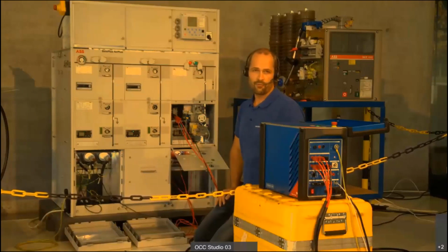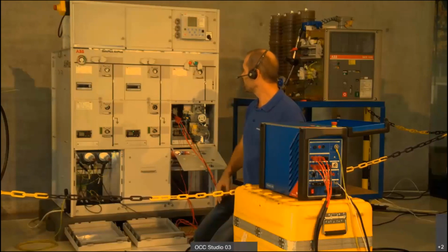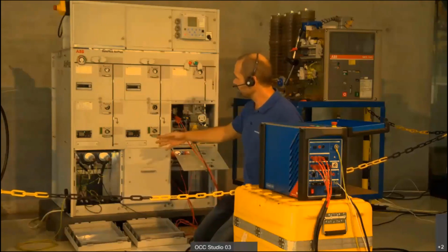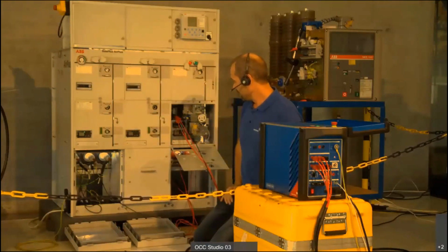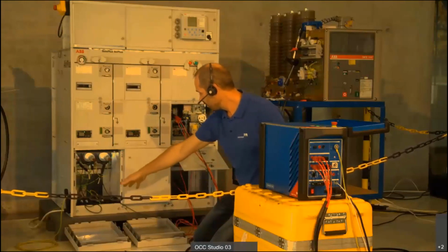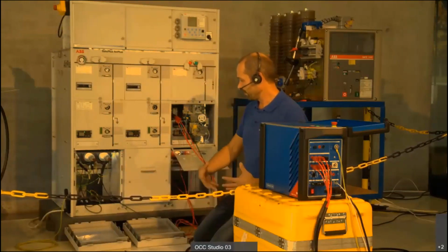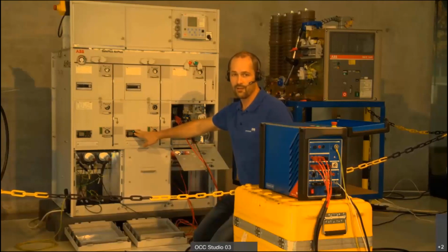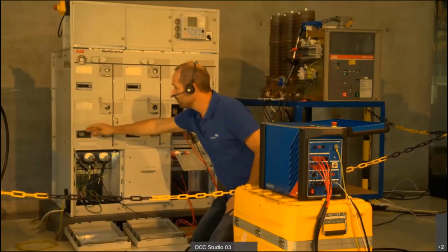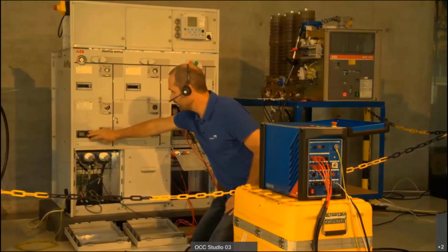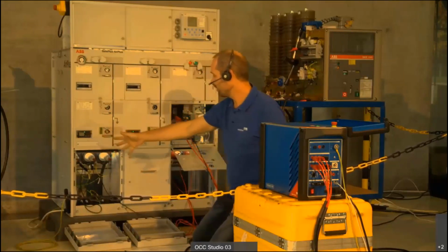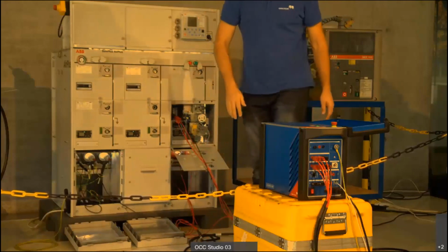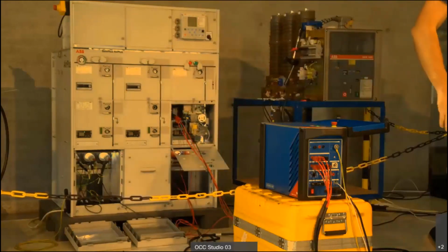The main feature of this type of breaker is that the primary path is encapsulated. It is sealed for lifetime, so there is no other way to access the main contacts of the breaker or any other contacts here. Therefore, you have to use those connection points here, and if they are already used and not possible, then the only way to connect the primary are these VTM features you see here. So we can use the VTM test for that. But to compare it with a regular timing test, we're going to connect it in this example like here. So everything is connected for the regular tests.